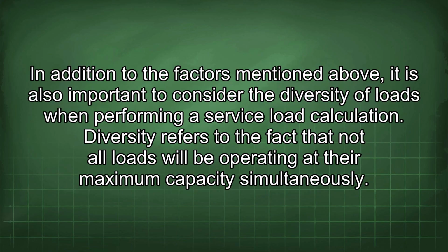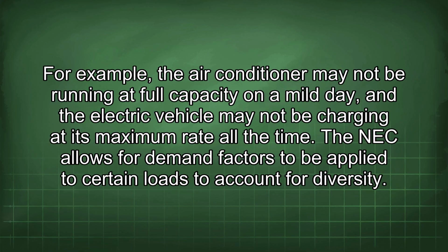In addition to the factors mentioned above, it is also important to consider the diversity of loads when performing a service load calculation. Diversity refers to the fact that not all loads will be operating at their maximum capacity simultaneously. For example, the air conditioner may not be running at full capacity on a mild day, and the electric vehicle may not be charging at its maximum rate all the time.